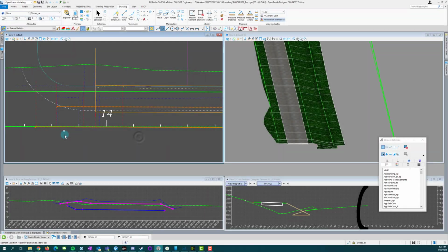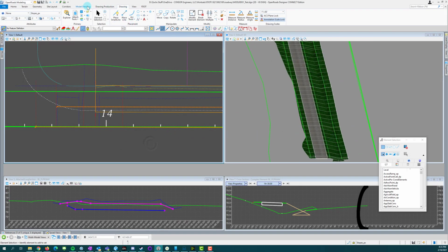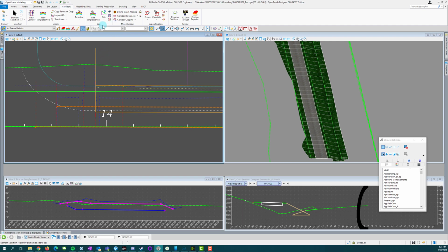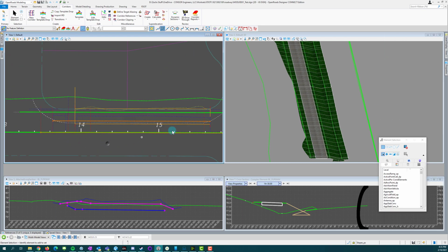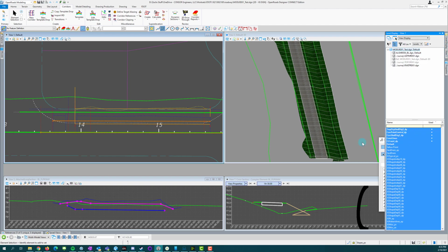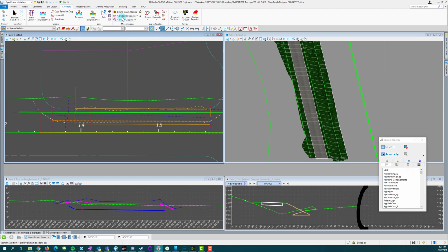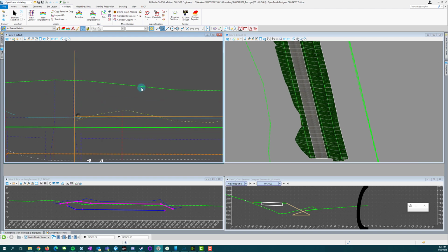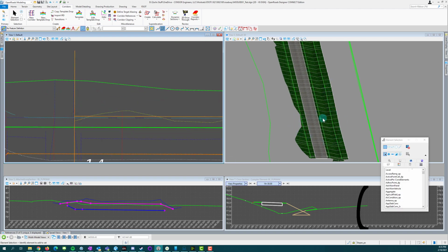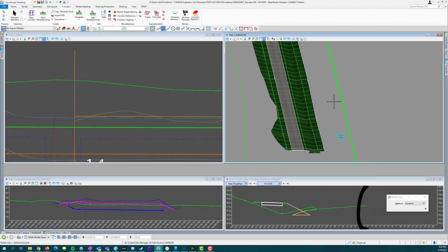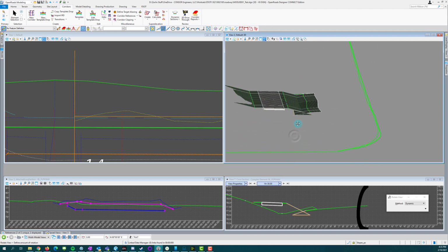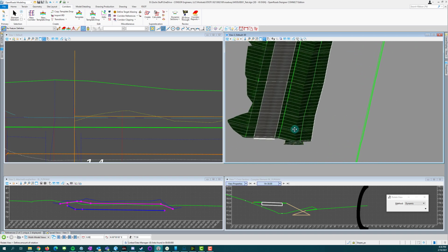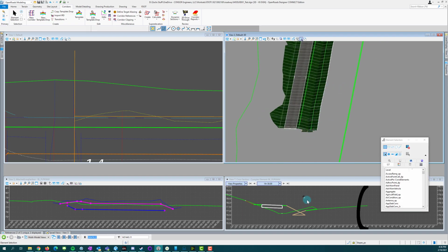So we're back. All right, so now we're back in the other file, and sometimes this will auto update for you, but other times you kind of need to do it yourself. So looks like this is one of those times I have to do it myself. Why don't I see my corridor? Oh, it's in there, it's hiding. We're just gonna update this. All right, so now we drop down. Man, this ditch is still kind of overlapping on us. So you can tell a ditch is overlapping when it starts doing that crisscrossy thing underneath. So that means your ditch is too low for it to work with this situation.